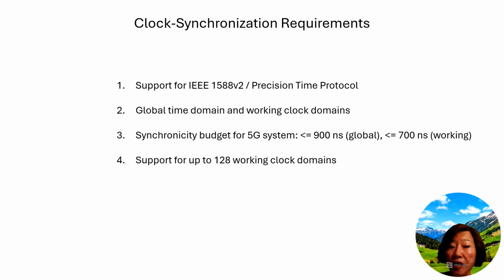The tight synchronization requirements also have implications for the hardware design of 5G equipment. Base stations and core network elements need to have very stable and accurate internal clocks, often using techniques like GPS disciplining or rubidium atomic clocks. The system also needs to handle environmental factors that can affect timing accuracy, such as temperature variations and vibration, through techniques like adaptive clock recovery and dynamic calibration.